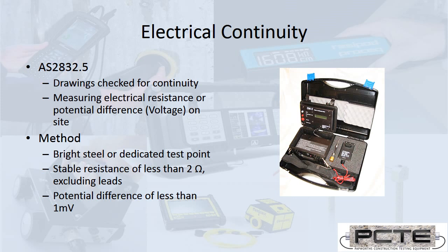When you are evaluating this, it's not as simple as getting the simplest multimeter possible and using that on site. It's important to get a good quality calibrated instrument, and usually to measure both the resistance and the voltages.